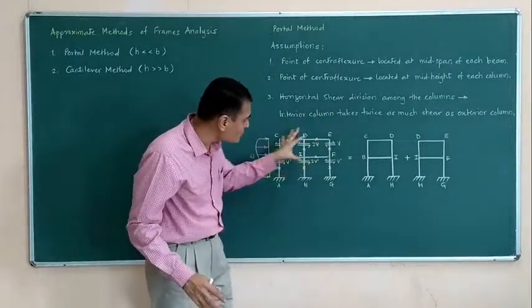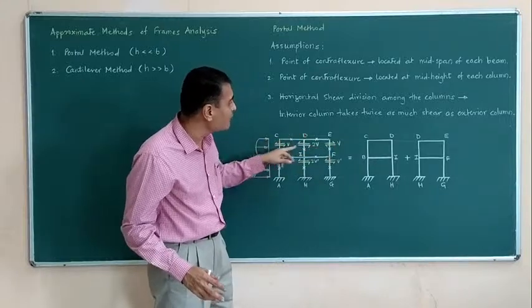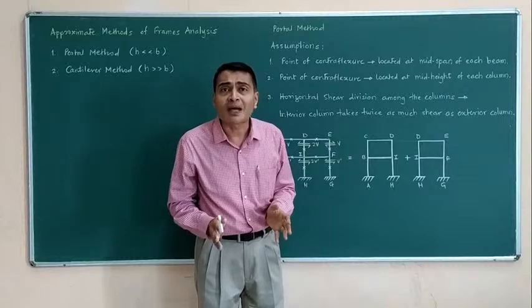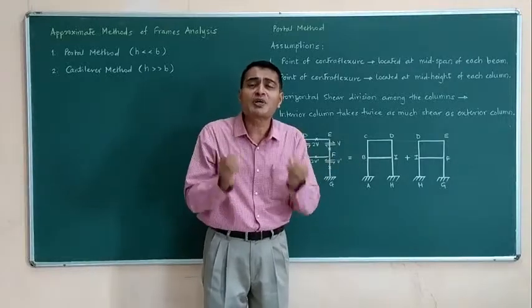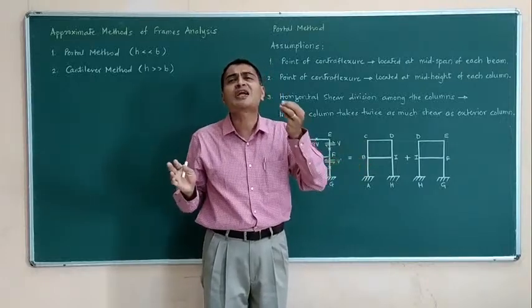That is the basis of this assumption. Now when we use these assumptions, V, 2V, V, and all these midpoints are the points of contraflexure, analyzing this frame becomes extremely simple. It just becomes a work of applying equilibrium equations. Simple static principle.